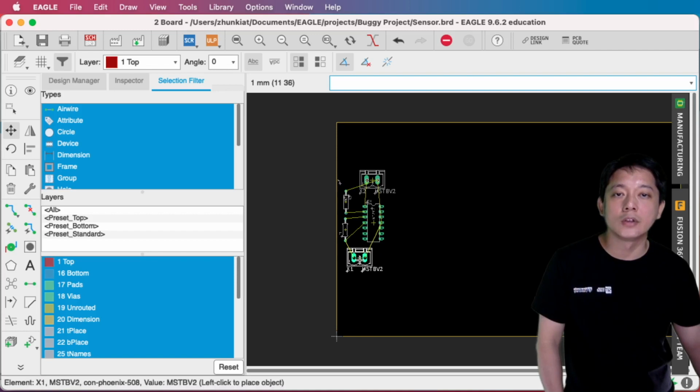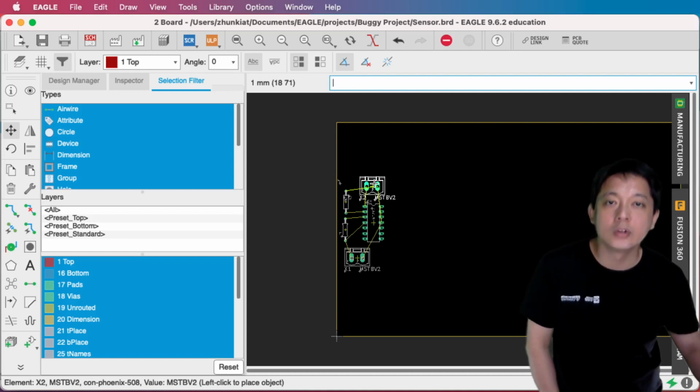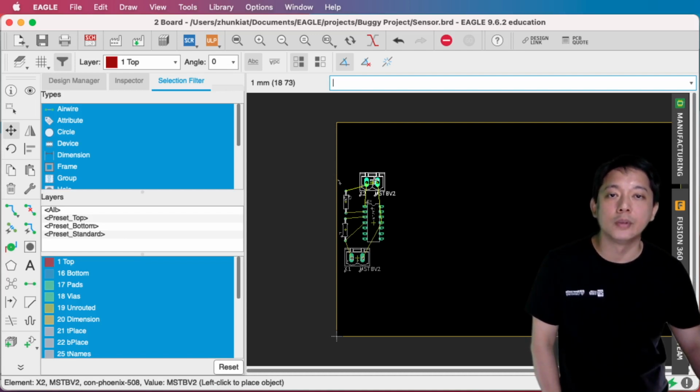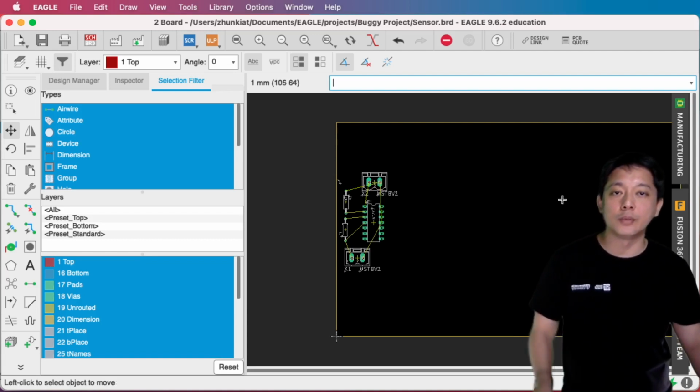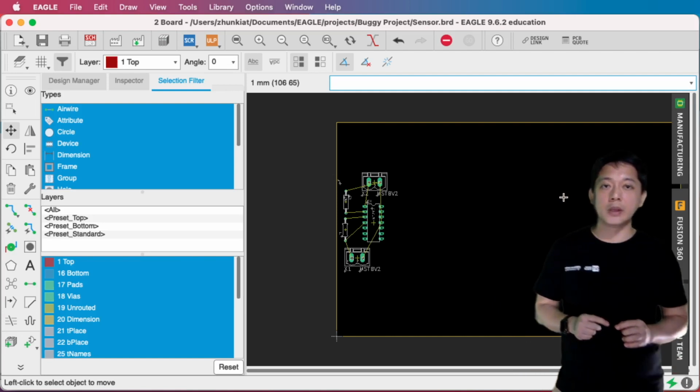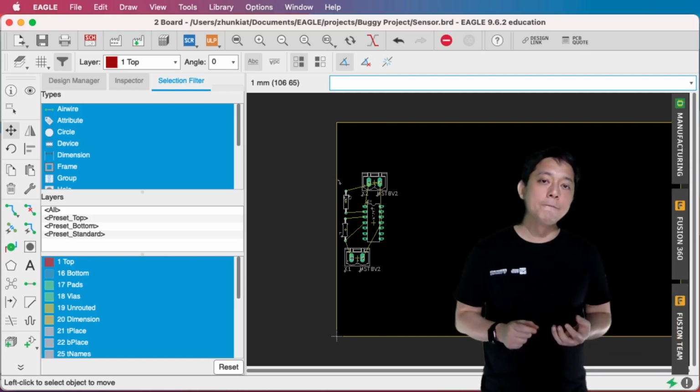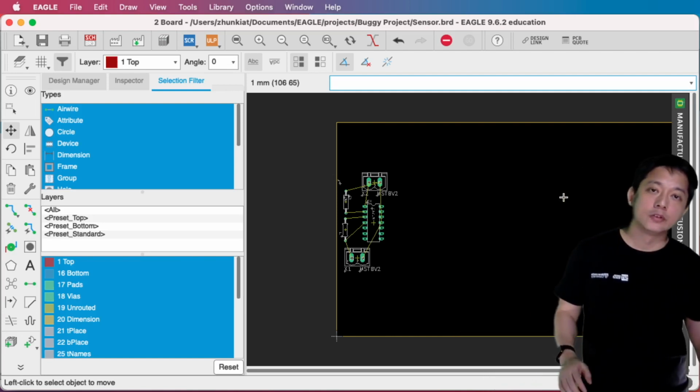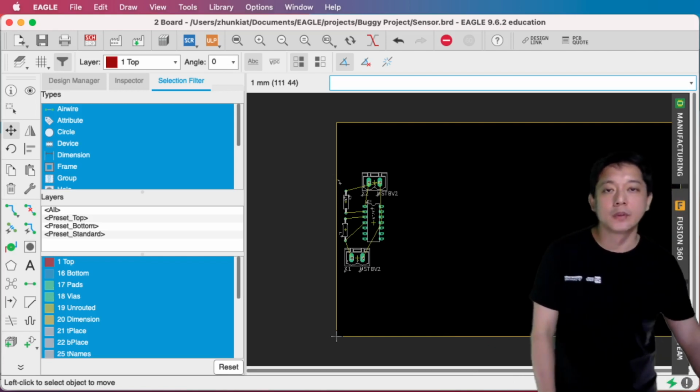This one I can compact a bit more, smaller. And maybe this one I can put closer also. As long as you don't overlap the footprint, you should be safe. Or if not, you can put a bit of spacing in between. Because sometimes the components are a bit big, and sometimes you do have wires joining them, so you might need some space for them.